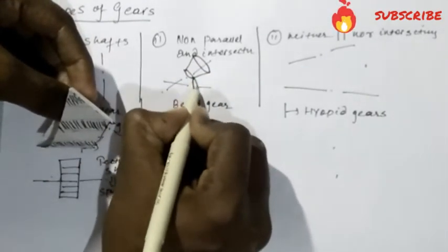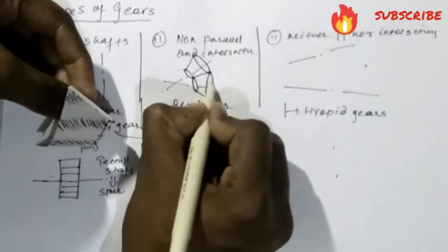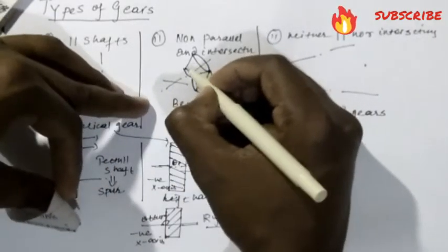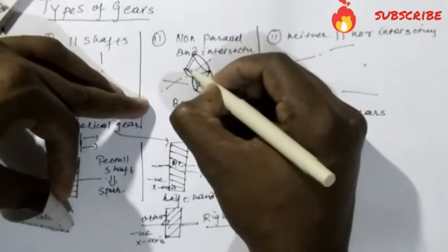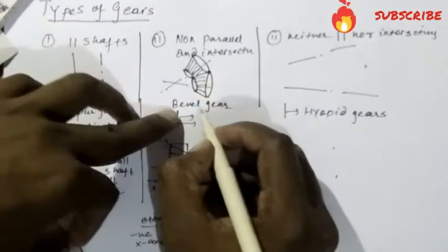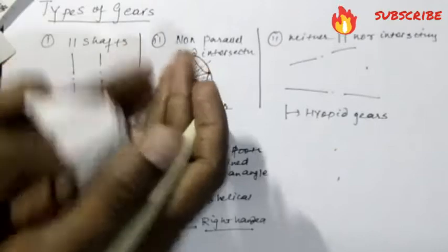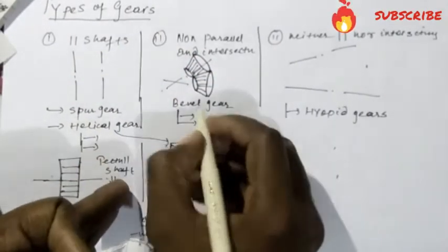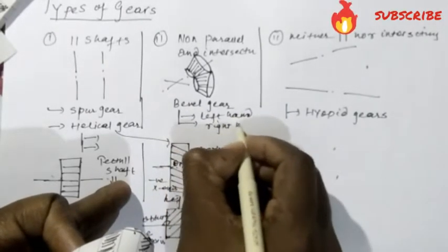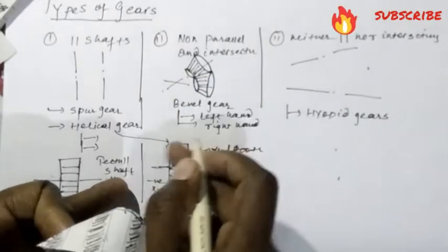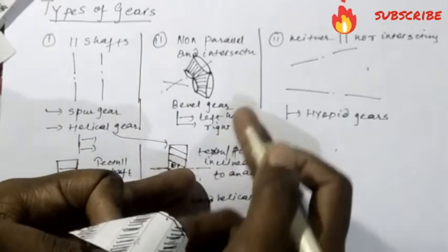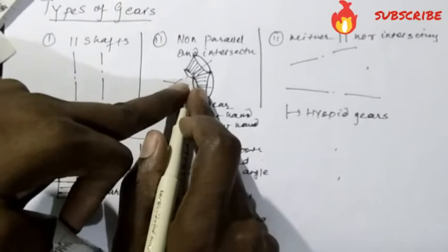Now the another bevel gear here, its conjugate. Now again the same case, the teeth can be parallel to the shaft, or inclined to the shaft. So the bevel gears will be again the same classification as there is the helical gear, left hand bevel gear and right hand bevel gear, and the same concept as it was in helical gear will be applied here in the bevel gear for its classification in left hand and right hand bevel gear. But you can see how bevel gear is there.